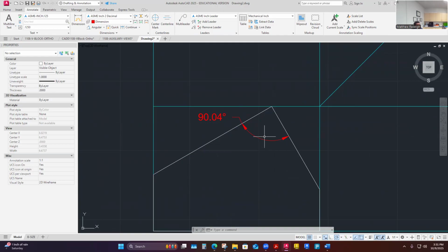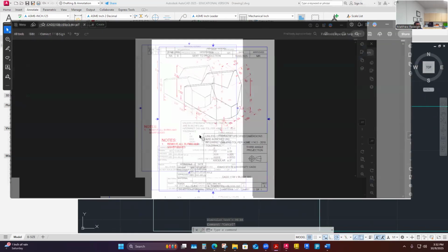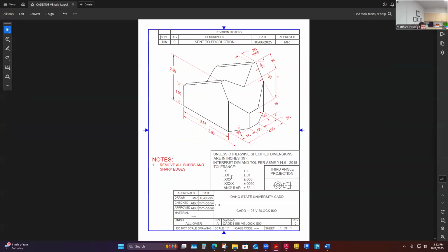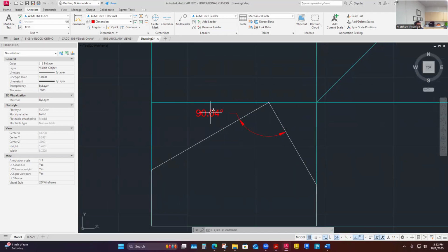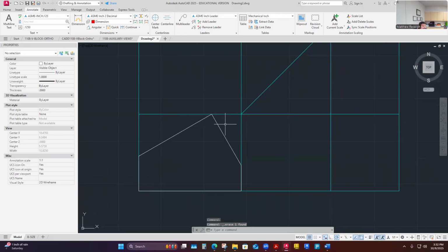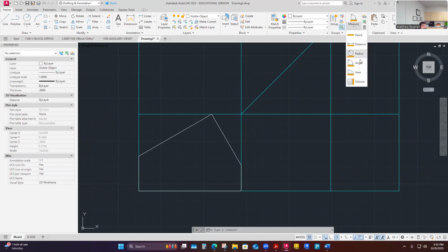Which maybe is correct, because my drawing is not even to any decimal places. So technically I have some tolerance applied there to the whole number. For angular, I'm plus or minus half a degree. I'm definitely within that tolerance, but this is where things can be hard to project from, and I'm technically not incorrect. I just want to point out that if I was holding to just whole numbers and no decimals, that would round to 90, like the angle measurement picks up.